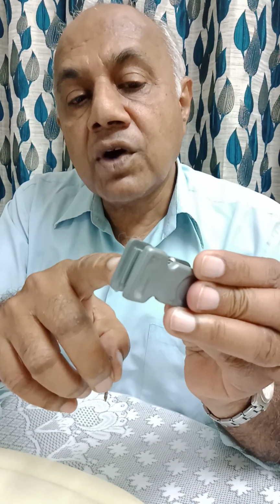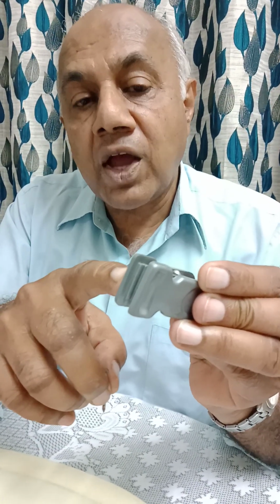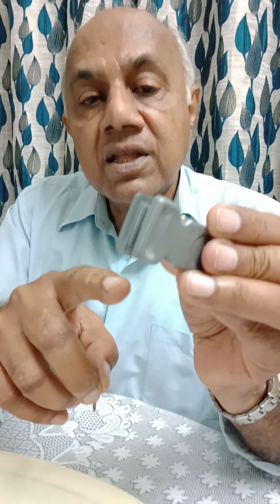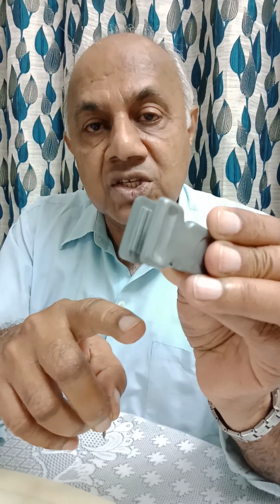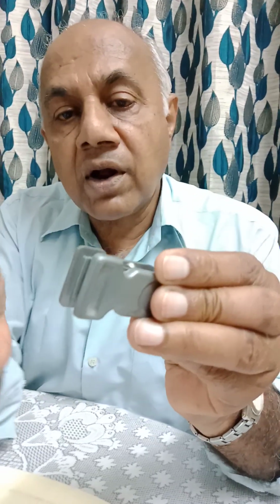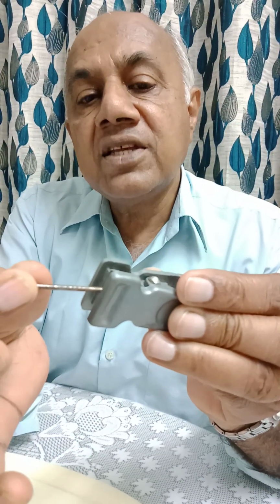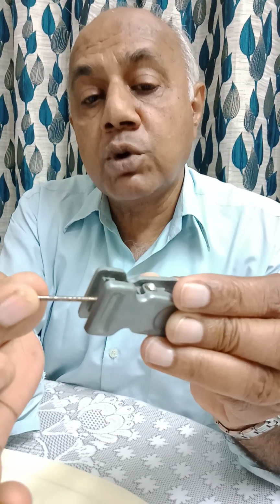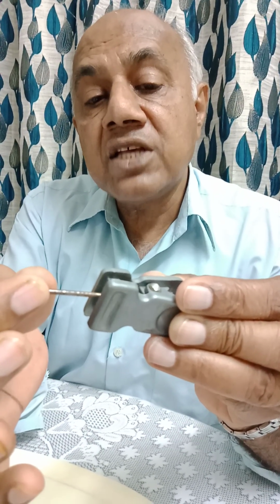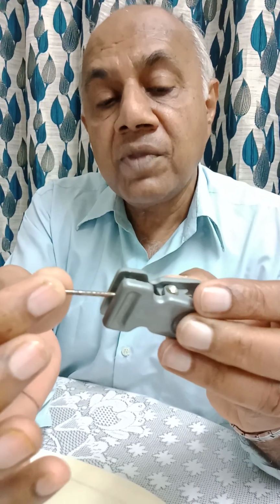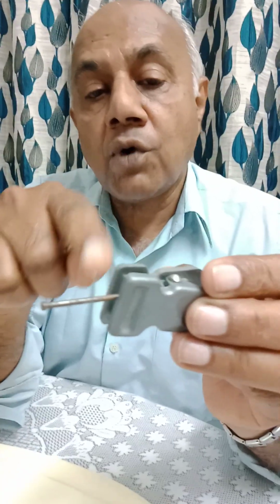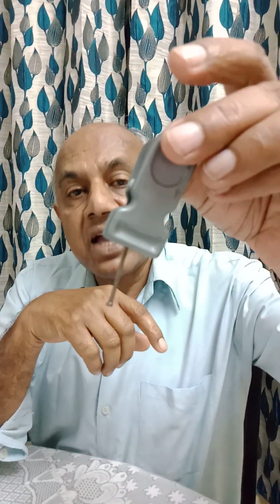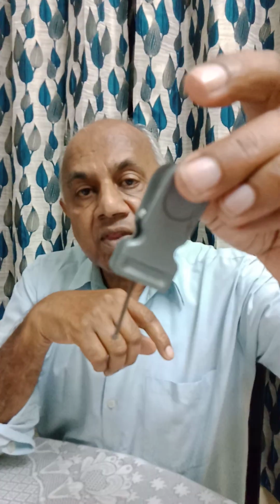The material of the wood, that is the wood fiber or the building material, gets apart like this, and the nail is held inside, slowly being pushed. Then this material tries to come to its original form by creating pressure on the wall and the nail, resulting in friction, and this is how a typical nail is held in its position.